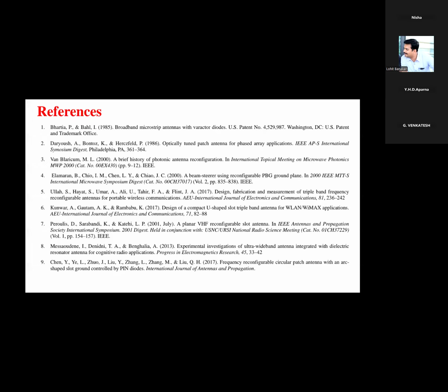Thank you. So now I'll discuss the meaning of correlation coefficient. Correlation coefficient is nothing but, when I place two antennas side by side, how much mutual coupling exists between the two antennas. When I design any MIMO antenna, the correlation coefficient value should be less than 0.5. You have to maintain this, meaning the mutual coupling should decrease. That is the main intention of the correlation coefficient.